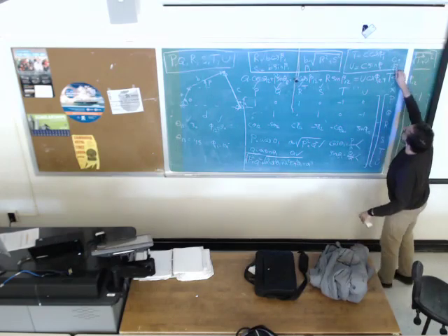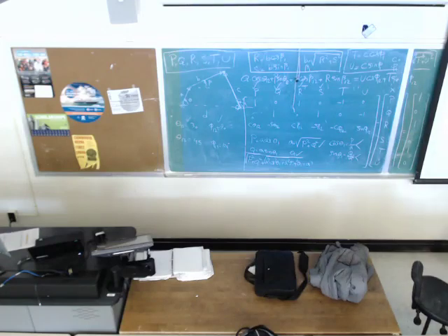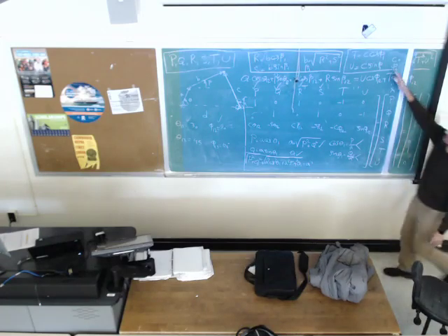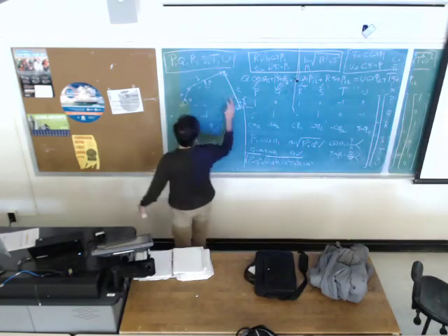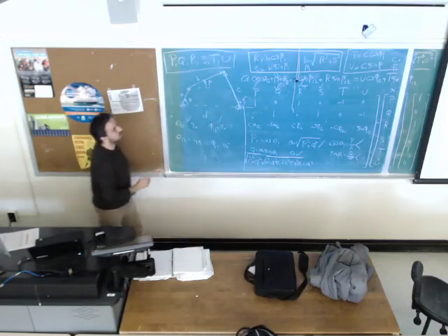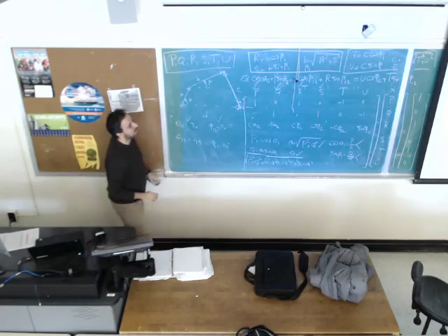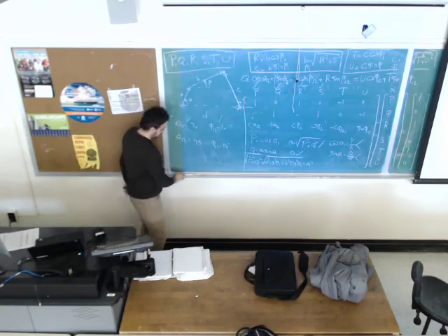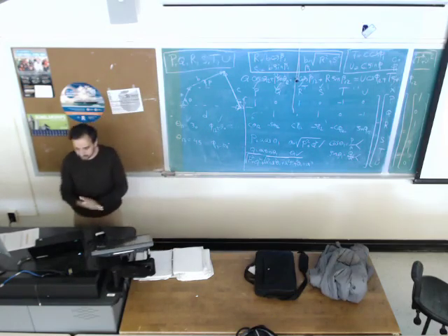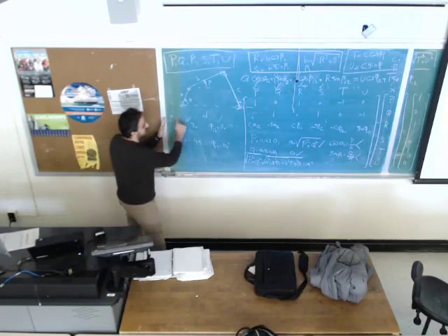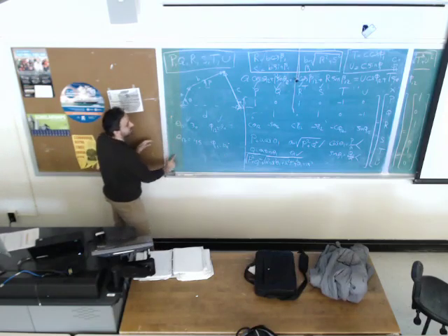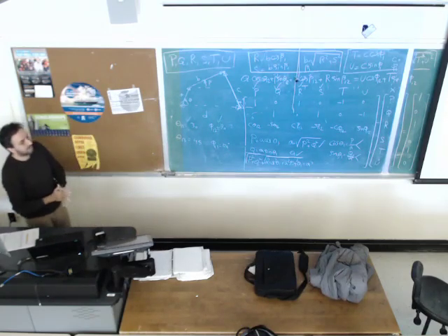After you find C, find phi 1 by finding the matching pair. So you find C and phi 1. So you can draw your mechanism at the first precision point. You are done with that because D is 1. So this mechanism is going to generate this desired function.